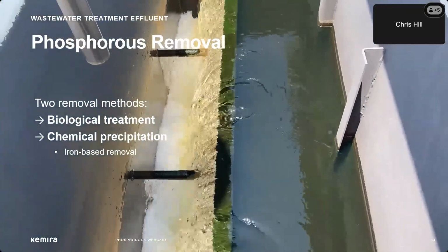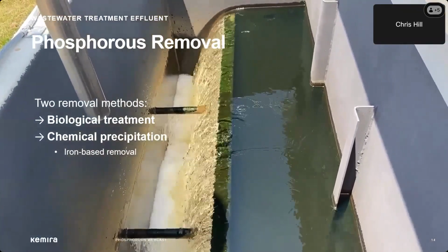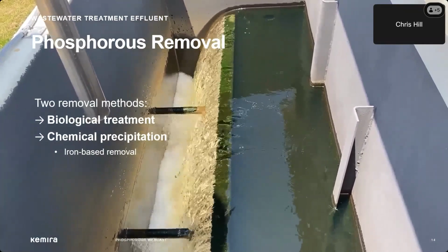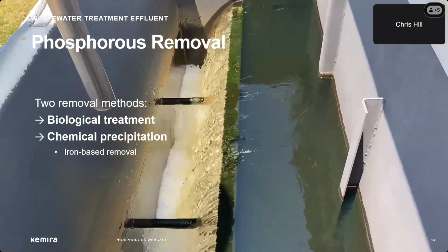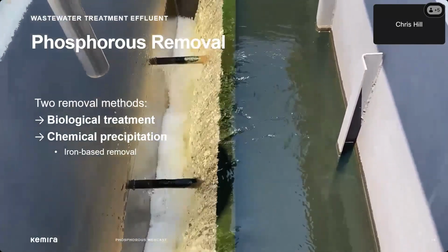Although there are several ways to treat and remove phosphorus from wastewater, the primary and most employed method has been through chemical treatment of wastewater using iron coagulants. Chemical precipitation using iron-based coagulants offers a robust, reliable, and fast-acting solution to phosphorus issues.